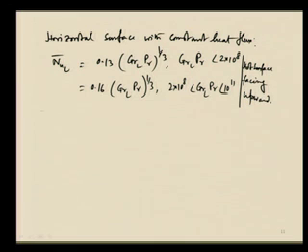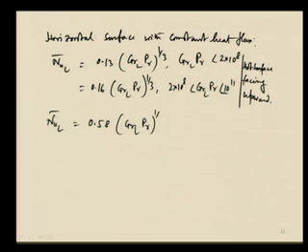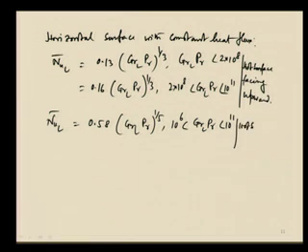Okay. And then there is another one, that Nusselt based on length, average Nusselt number, is equal to 0.58 into Grashof L into Prandtl to the power 1/5, and in this case 10 to the power 6 is less than Grashof based on L into Prandtl, which is less than 10 to the power 11. So, here the hot surface is facing downward.